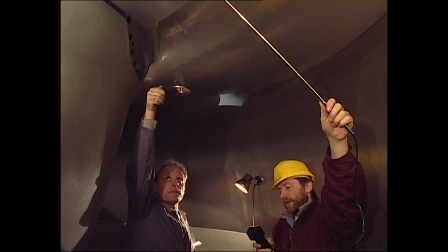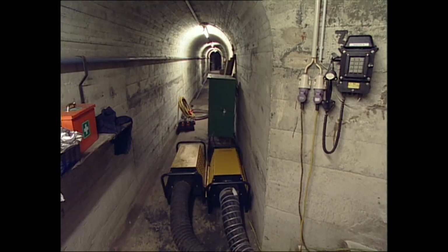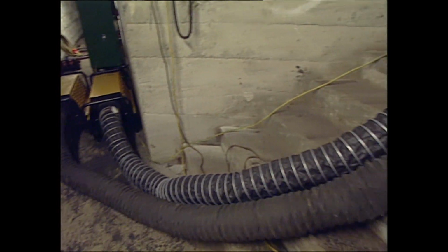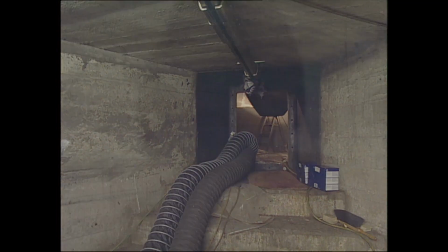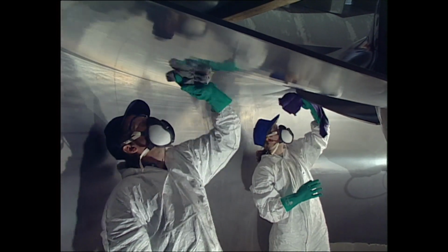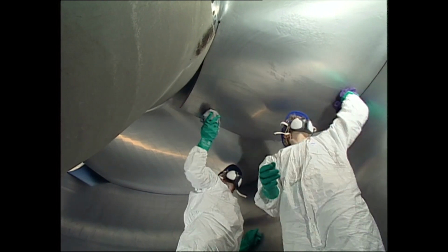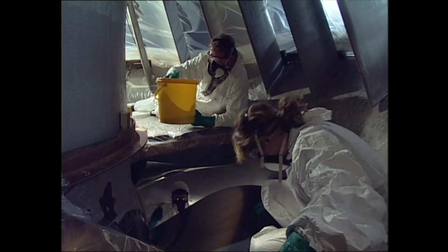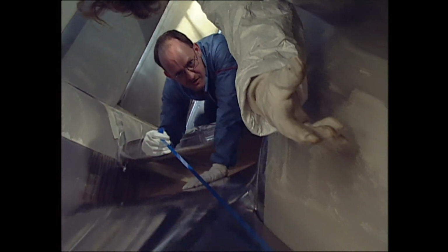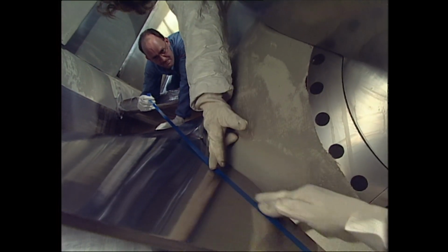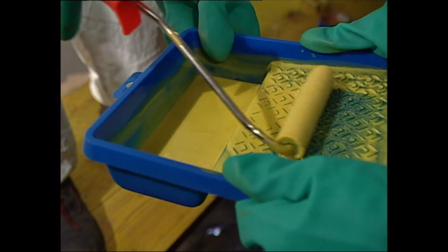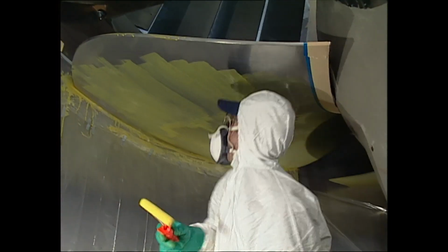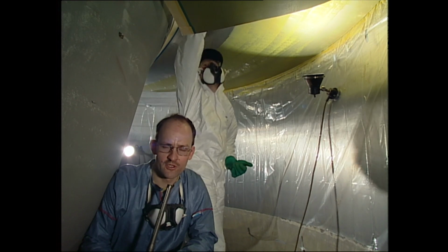The environmental conditions have to be closely controlled, mainly with regards to temperature, humidity and ventilation. A careful degreasing of the surfaces which are to be coated is essential for the success of the coating. To maintain long-term adhesion, a chemical surface pre-treatment has to be applied prior to the actual coating. In this case, we use a polyurethane soft coating.